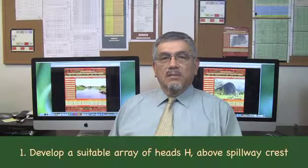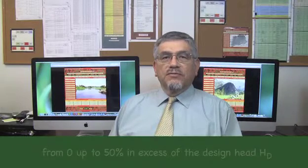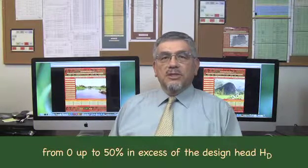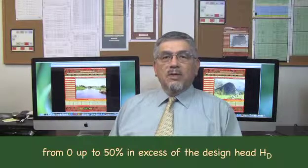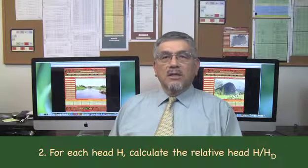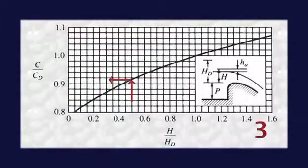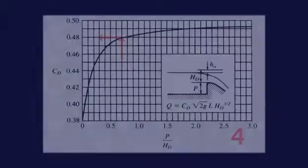A step-by-step procedure to develop a spillway rating is the following. 1. Develop a suitable array of heads H above spillway crest from 0 up to 50% in excess of the design head H sub capital D. 2. For each head H, calculate the relative head H over H sub capital D. 3. For each relative head H over H sub capital D, enter this figure to determine the relative discharge coefficient C over C sub capital D. 4.